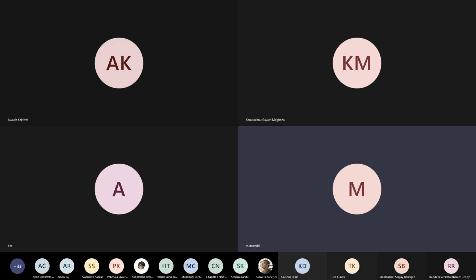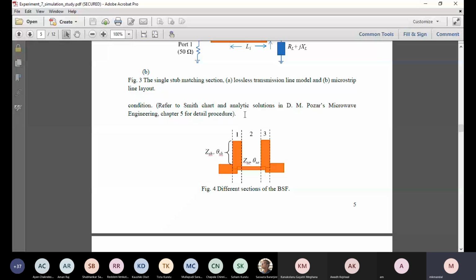Well, first of all, last time we discussed ABCD parameters, and I referred to a table given in Pozar's book. Once you have ABCD parameters for this whole band stop filter unit, you can convert them to S parameters using the formula given in Pozar's book. But it seems that you did not try it, otherwise you would report some problem.